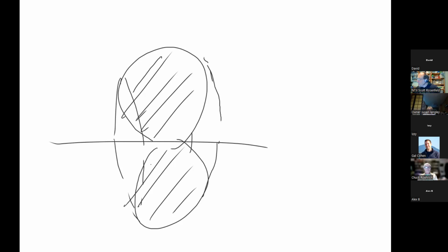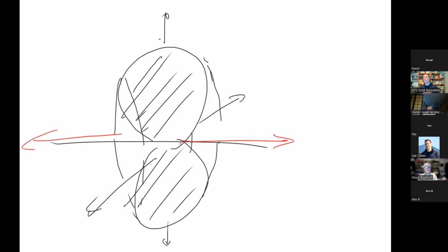And so a dipole would generate energy upward and downward and toward us and away from us. And it generates absolutely nothing along the axis of the wire. Okay, so can you think of any good things about this? Physical installation problem? Yeah, well, I mean, good things. You can put this up on a tower and rotate it, right?